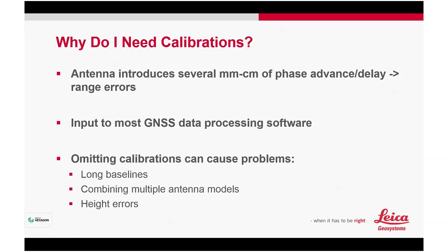Okay, sometimes people say, hey, the horizontal is correct, but my vertical is 10 centimeters different. Okay, I can tell you most of the time it's because the antenna file is not used correctly when you do the post-processing.